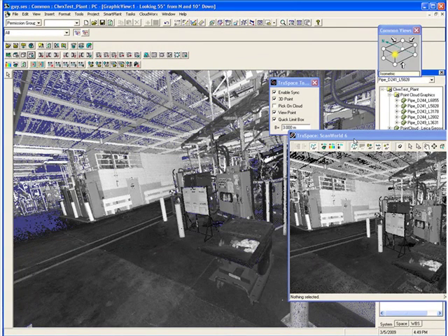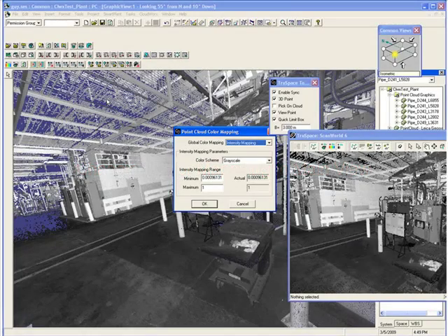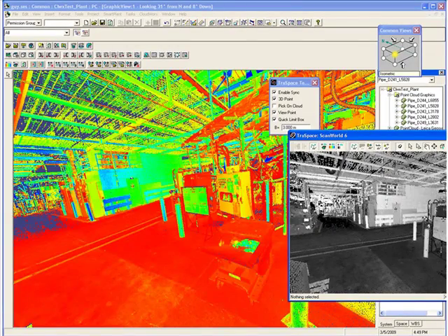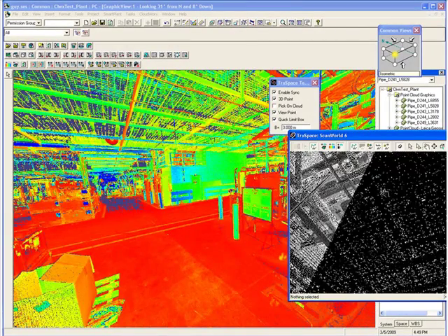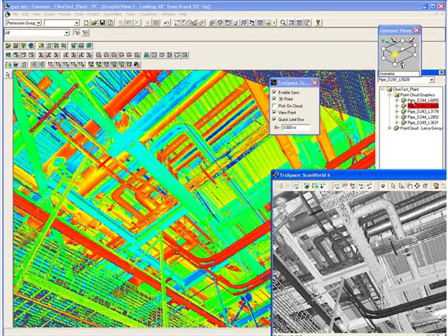You can also change the rendering in the main area by hitting this button here. Maybe you want multi-hue. Okay, you can, and then you go to a multi-hue view. Some people like this because it's brighter. If I go up to maybe this section here, you can see here that it really shows out quite well. So it's really easy for you to pick out these pipe runs and create all these center lines and then connect them. And you're creating actual PDS elements here, graphical elements, that you can then assign more intelligence to later on.